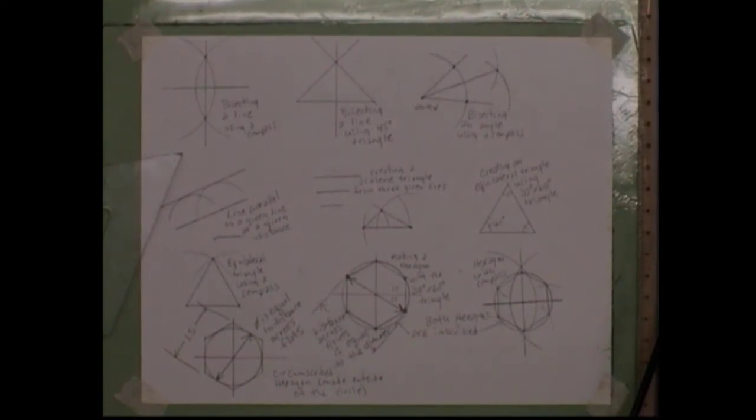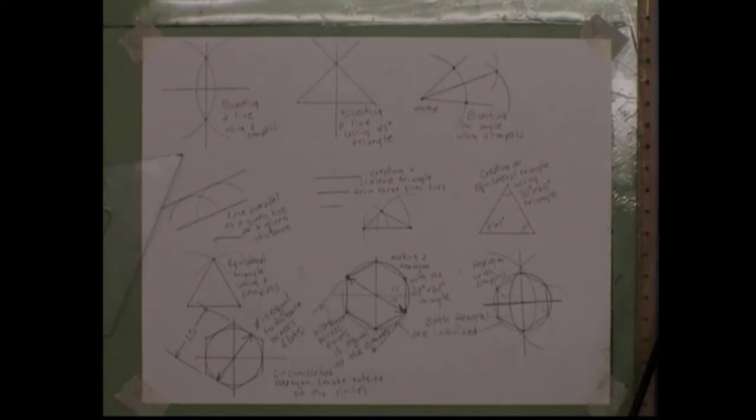So you click on the center. Then it's going to say, what's the diameter? And you would tell it 1.5. Then it's going to say, do you want this inscribed or circumscribed? In this case, what would we have to choose? Circumscribed. Correct? Because it's made outside of the circle.